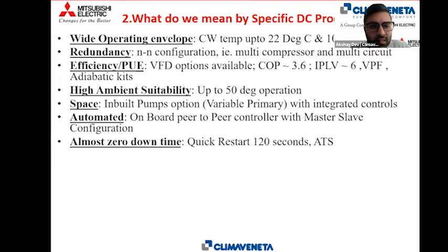This is a controversial statement, almost zero downtime. Of course, any customer will say they want zero downtime, but when it comes to a DC product, please ensure that you choose a product which has a quick restart. Gone are the days again where products used to start in around 300, 400 seconds. Today, you cannot afford it. The full load has to be achieved in 120 seconds, and your chiller should start in 30 seconds.